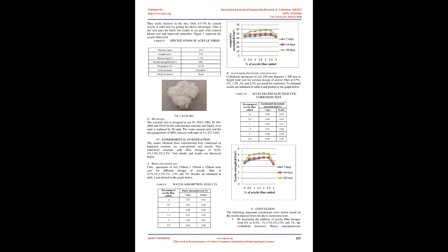C. Coarse aggregate. It should be hard, strong, dense, durable and clean. It must be free from veins, adherent coatings, an injurious amount of disintegrated pieces, alkalis, vegetable matter and other deleterious substances. It should be roughly cubical in shape. Flaky pieces should be avoided. It should conform to IS 383. Coarse aggregates used are of 2 sizes: 20 mm maximum size and 12.5 mm minimum size.